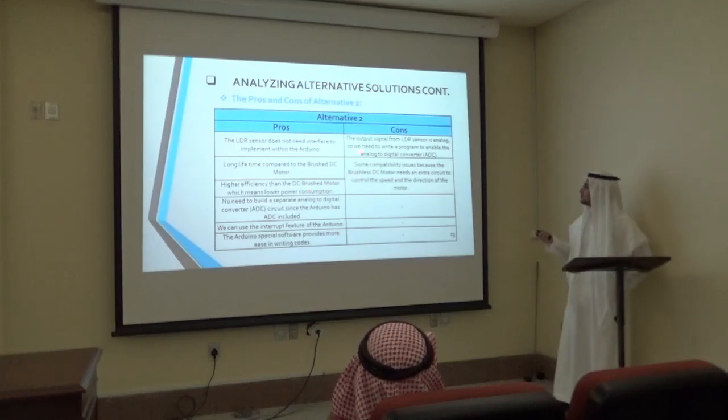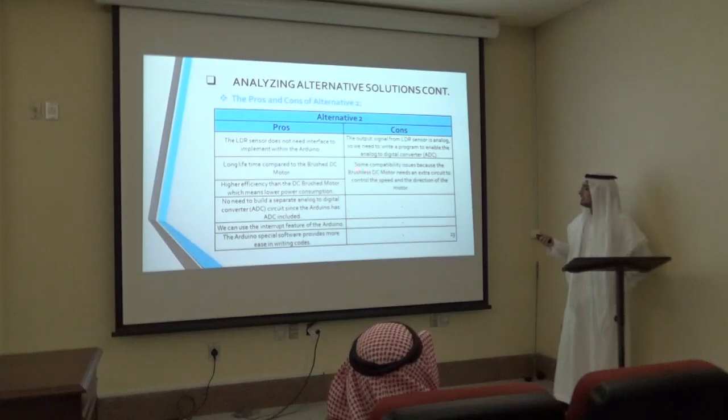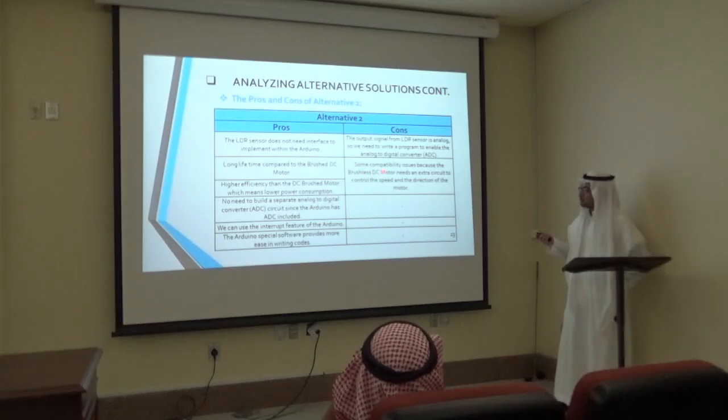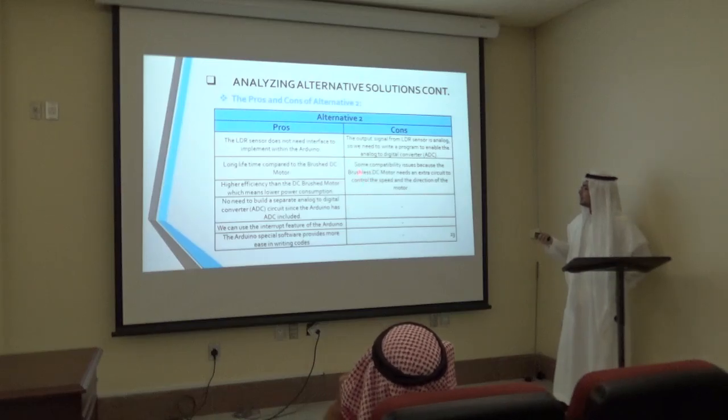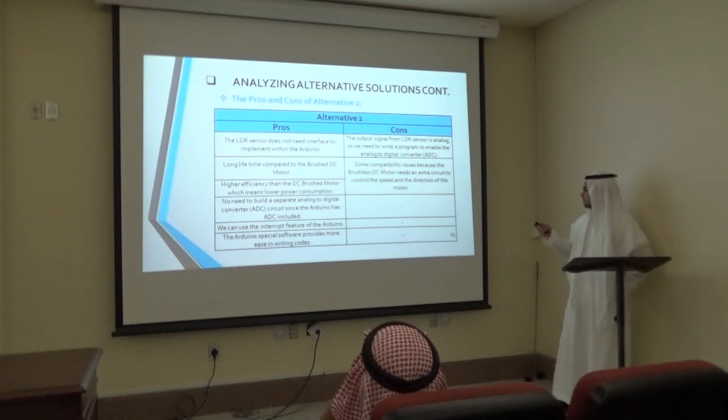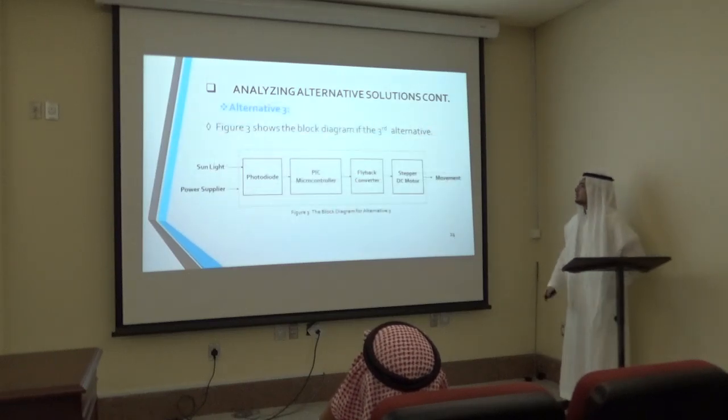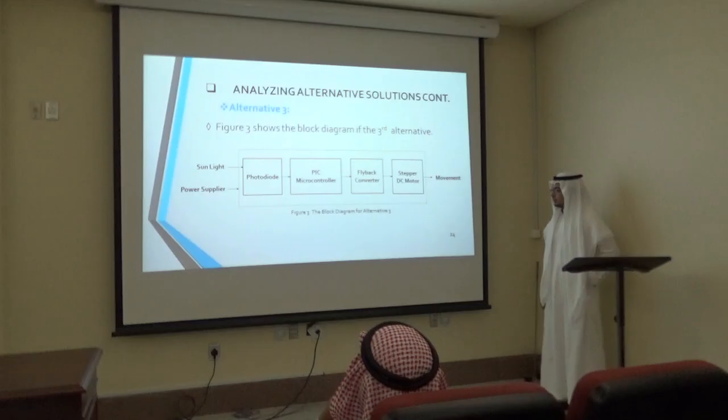But there is some problem in this design. The brushless DC motor needs a specific driver to change its direction. So the boost converter will not do this job. So let's go to the third alternative. This is the block diagram.